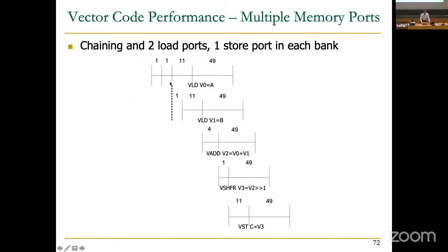So this is basically you start the first load in cycle 1. The second load is completely independent of the first load. It can go to the other load port. So you start the next load. So basically you almost completely overlap the latency of these 2 loads because they access 2 different ports in memory. Of course, 2 different ports is expensive, right? Clearly, 2 different ports is really 2 different address buses and 2 different data buses. But then, of course, it's shared across banks. But still, it's expensive. But you could parallelize.